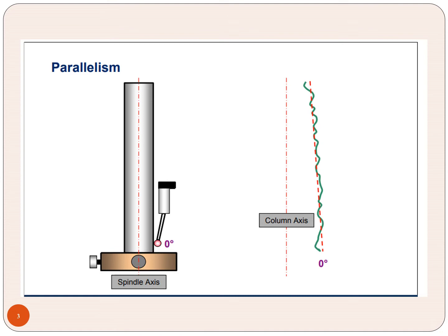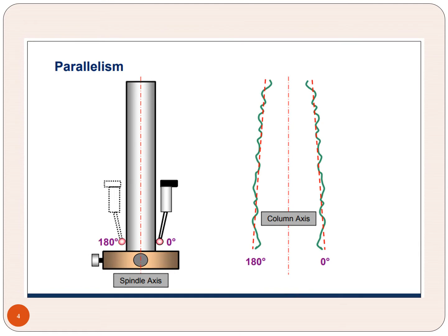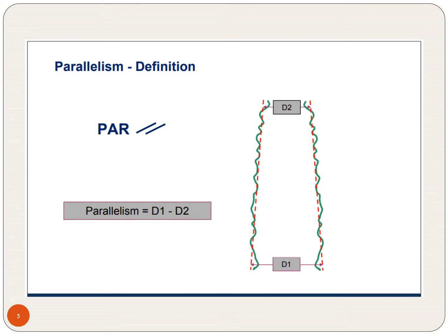So that can also be measured by using this method. This is double side we are measuring of a cylinder, and we are finding the error in the circumferential direction. So the parallelism is not there. Even for cylinders, we have this much error.